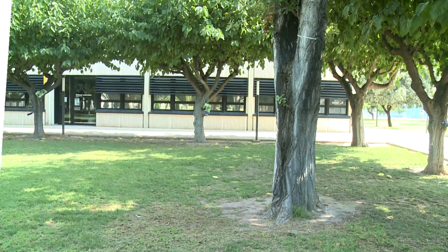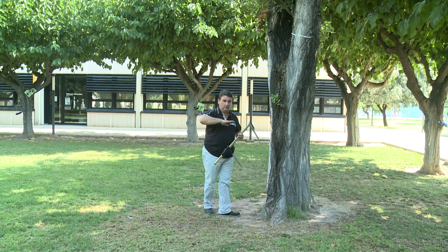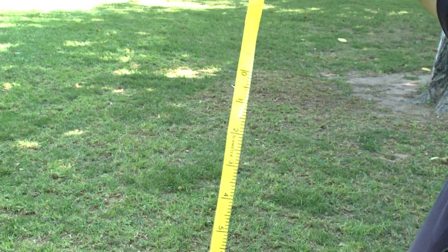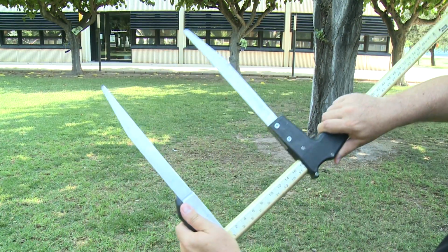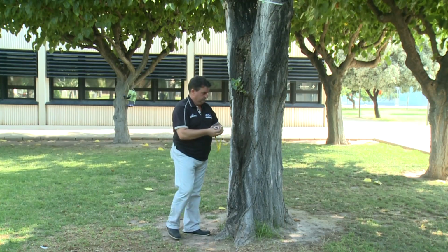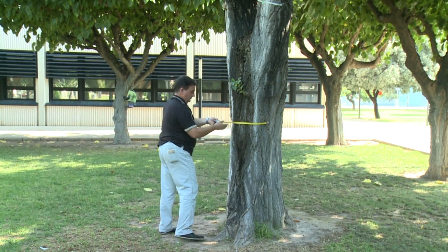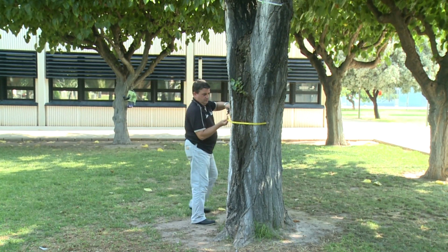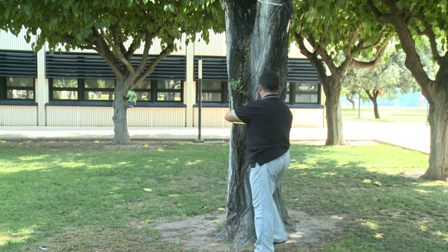The basic data of the vegetation structure inventory is the tree diameter. It is usually measured by the diameter at breast height, the DBH, at 1.3 meters tall, by tapes and forestry calipers. If we use a diameter tape, we should embrace the DBH section with the tape, cross both sides of the tape, and read directly the diameter data.